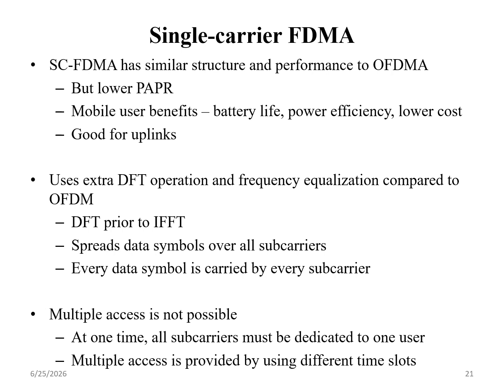Next, what are the issues and how are they overcome? With the help of single carrier frequency division multiple access. SC-FDMA has a similar structure and performance to what we have discussed in OFDMA, with the advantage of lower PAPR. If you use single carrier FDMA, the PAPR will be very low. If you go for OFDMA, the PAPR will be high.